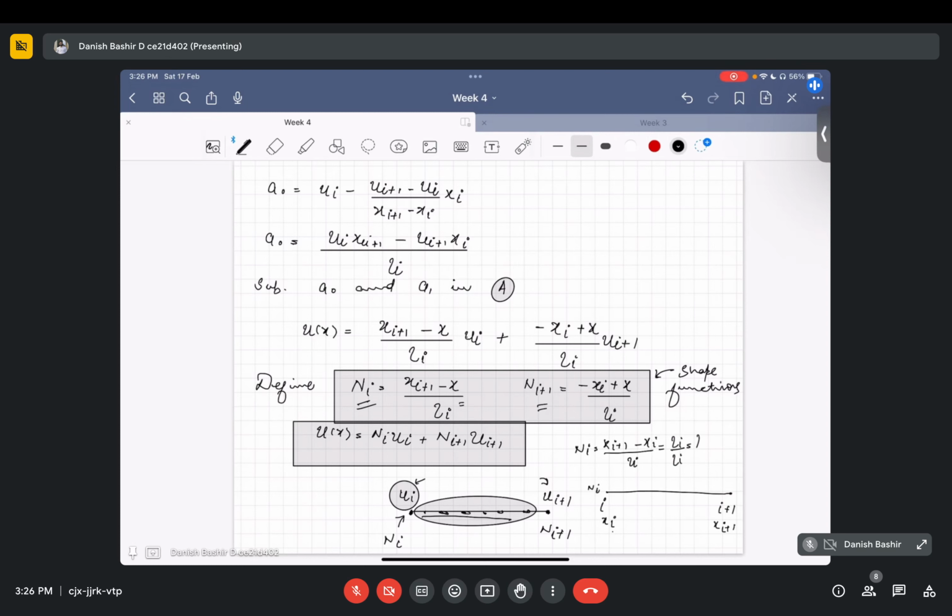So the value of this shape function at the node itself comes out to be equal to 1. And if you put x equal to xi plus 1 here, it will come out to be 0.